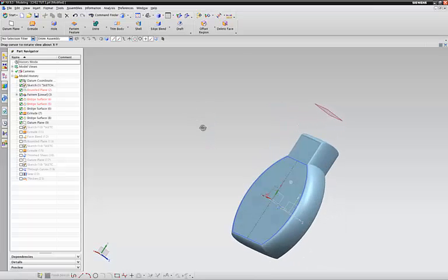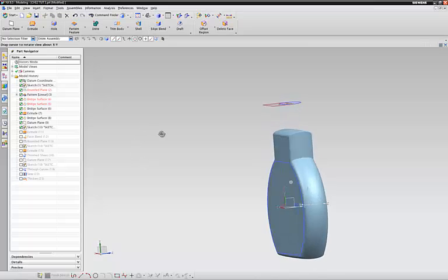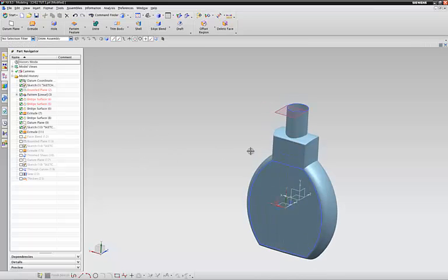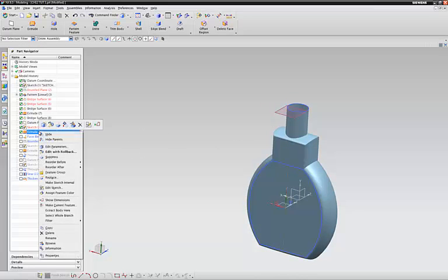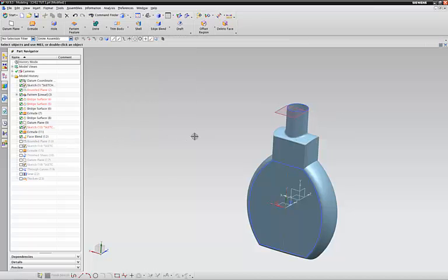Put in our datum plane, so we could do a sketch of that circle, which is centered. Extruded it down to next. Oh, we just moved it down 25 on this one. Another one I extruded it down to next.